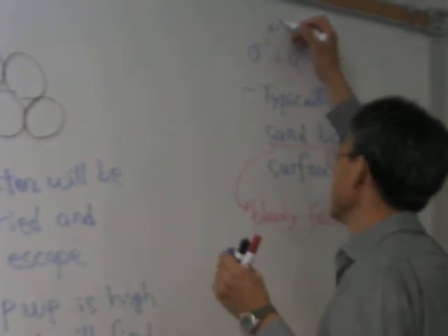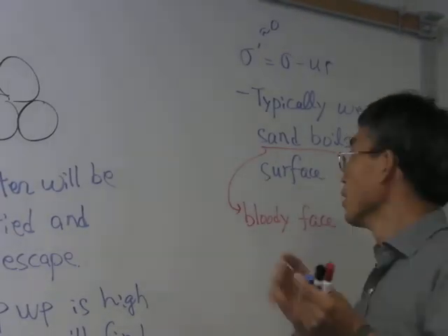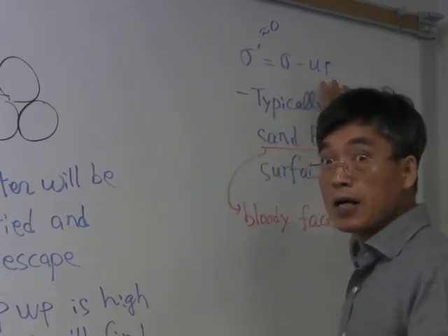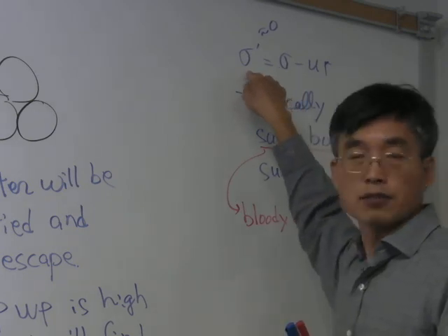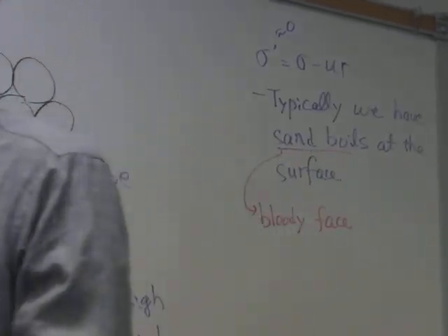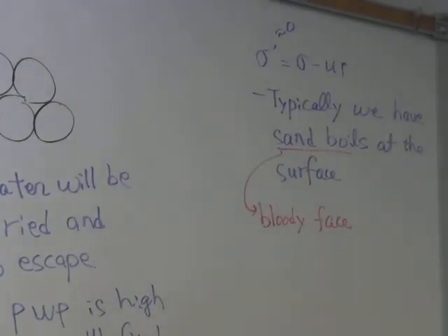Well, how do you determine the magnitude of the liquefaction, or do you just say liquefaction occurred? There is no magnitude of liquefaction, okay? Because liquefaction is the condition when this guy is high enough and this guy will close to 0. If this one is high but not very high, so that this one is still not 0, then it's not called liquefaction, but it may still cause the troubles. So that has to be right at 0.